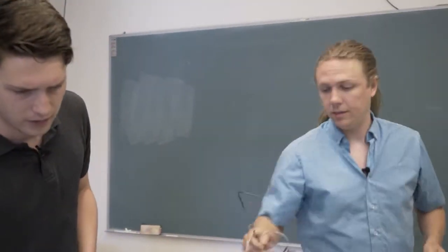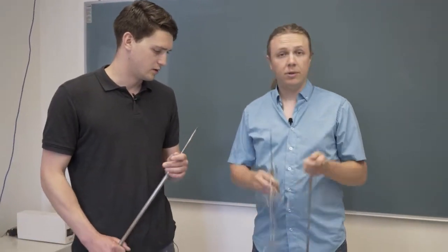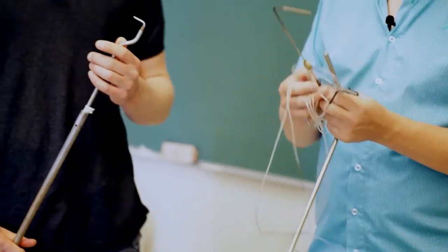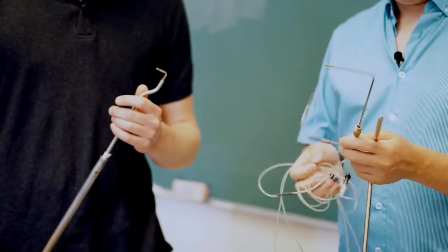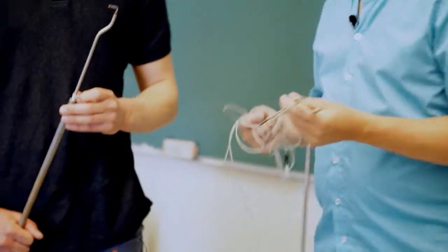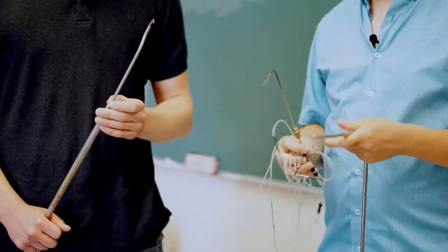I think we have a couple examples, various geometries here of different pitot tubes. Let's go through what applications you can get from these. Sure. So pitot tubes come in all shapes and sizes. We can put compression fittings on them, so we can install them into the walls of ducts or into pipes. We can stick them out the side of airplanes. So airplanes are an important place that we use pitot tubes. When we put them in an airplane, we'd heat these because they can ice at altitude, so they get fancier than this. Or even as simple as a bent piece of tube is the simplest pitot tube you can make.